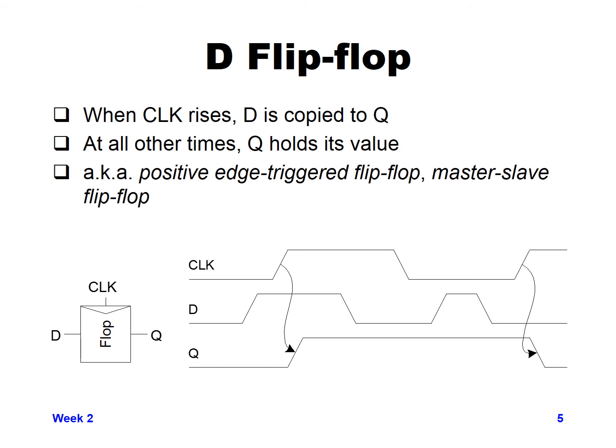So we will take that value and copy it, or transition it, through to Q. Q will go to 1, and it will hold that value of 1 as D keeps switching several times, and the clock also switches from high to low. Nothing happens to our value of Q. Q stays stable as long as there isn't a transition of the clock from 0 to 1.